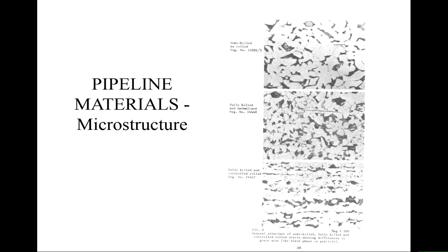On the top image, it looks like the grain size is a lot smaller towards the top of the image. It is, yes. Position against the rollers. This was quite a thick plate, and a lot of the deformation is done by gripping with the roller, so there's a lot more shear next to the roller than there is in the middle of the plate. Because pipe steels tend to be quite thick, you do get this gradient of properties across the material. If you're talking about a car body sheet, which is also cold rolled, it's only a few millimeters thick, you don't see this variation.